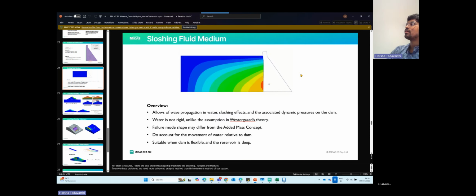So yes, we can actually apply the factors directly in the load, or we can simply apply the load combination that we had created in this software. So we can do both options in this case. So we can go for combinations via factor and then apply it in the analysis as well.